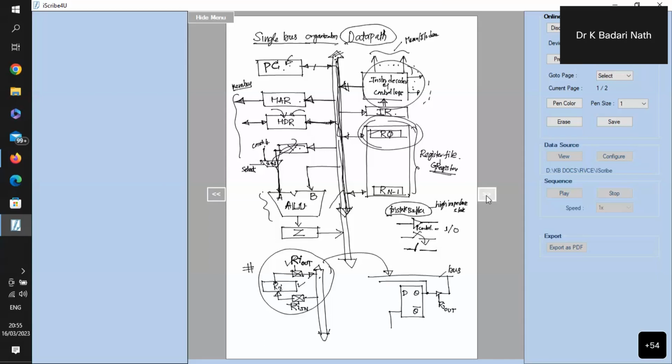The clock is a common clock signal. Let's say edge-triggered flip-flops or edge-triggered clocks are commonly used to design the processor. When the clock is supplied at one place in the processor, every block will get the clock. That means when the clock is given, if you're not writing new data, the old data will be retained. Sometimes the data should come from Q, and sometimes new data should be able to come in. So there are two possibilities, and I will use a 2:1 multiplexer. One input is this data, the other is this data.